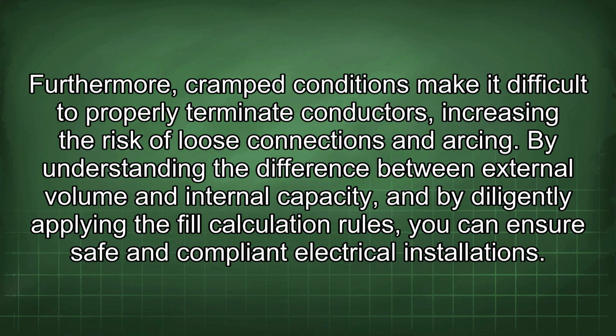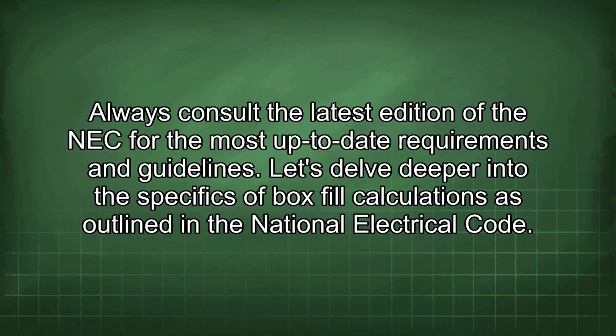By understanding the difference between external volume and internal capacity, and by diligently applying the fill calculation rules, you can ensure safe and compliant electrical installations. Always consult the latest edition of the NEC for the most up-to-date requirements and guidelines.